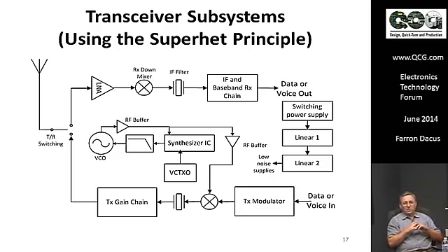And the way is to use direct sequence spread spectrum and chip up to a higher data rate. You use a wider filter, but then you get this artificial noise bandwidth narrowing due to what they call the processing gain of the direct sequence. So it sounds real fancy, but basically it's just a way to get ultra narrow bandwidth. There's a couple of chips out on the market that do this, and if you can get data rates of like 100 bits per second and noise bandwidths of 100 bits per second, then you drop a 6 dB received noise figure on top of that, and you're at about the limit of physics.